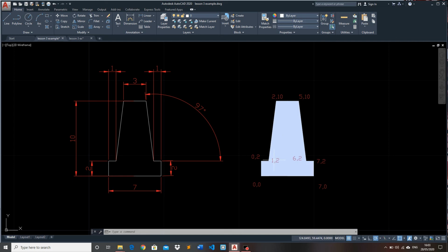Please try to draw it using either absolute coordinate, or relative coordinate system, or polar coordinate system, or you can use a combination of all those, as in normal drawing. Or you can draw it simply using what we call the cursor, but it will be difficult. So you can use this thing to help you and guide you.